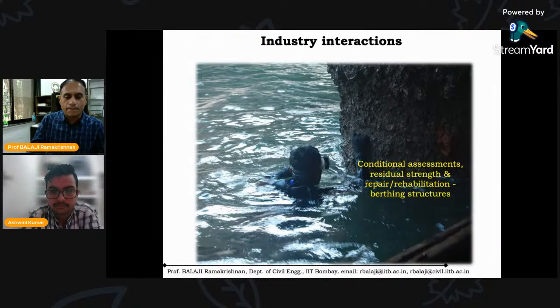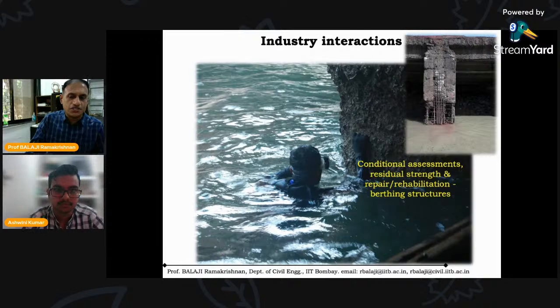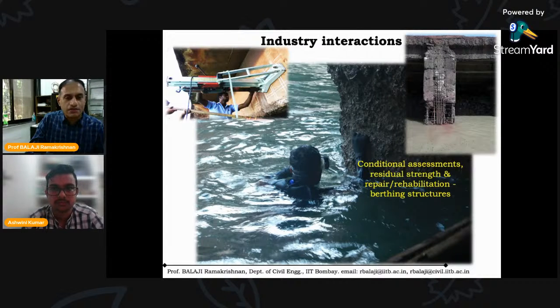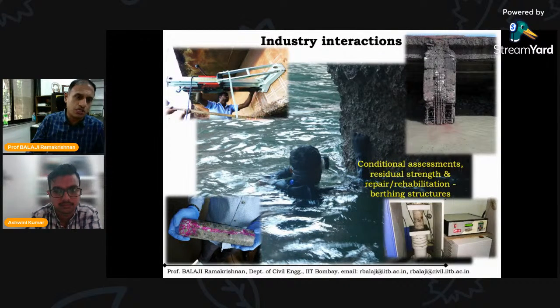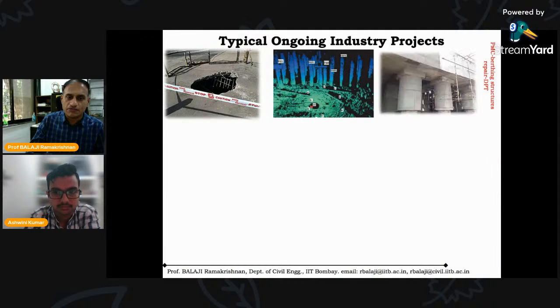Currently, we are also working on condition assessment. As you know, civil engineering infrastructure is going to face age-related issues over the years, and marine structures usually reach this stage very fast. So we work with port industries to understand how bad the condition of the existing infrastructure is. When we have to decide whether to demolish or repair, we need strong, engineering-information-supported decisions. So we do field tests, lab tests, and modeling, and then come to a conclusion to continue with the structure or replace it with a new structure. I think with that I will try to stop.